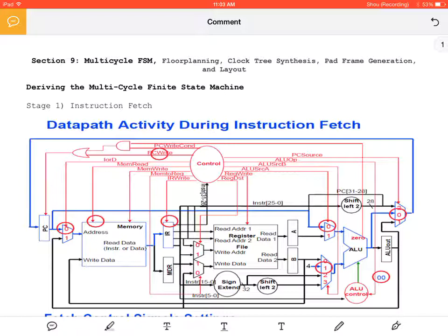So you know you've properly designed the PMOS section, right? And you get 20 errors in the Electric VLSI tool. It actually has the rules. So let's say you go through and say, okay, I got this error and this rule is this, and it's in the layout, it's in your TGOs. So I looked at it, it appeared fine, I can't figure it out, I tried moving things around, and it didn't work. Show me your attempts, show me what you've actually attempted to do to solve it. If you do that, you've shown me that you've made an honest attempt. It shows me that you understand the underlying CMOS, and it shows me that you understand troubleshooting.